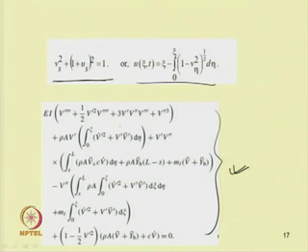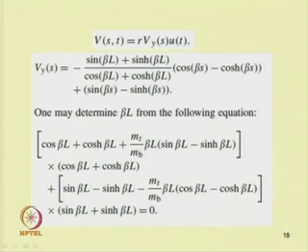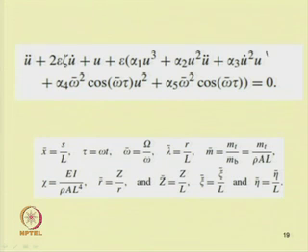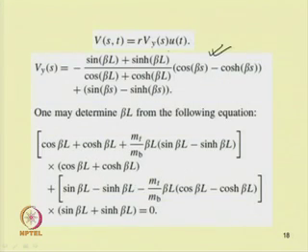After getting the equation of motion in spatio-temporal form, by substituting the shape function one can find the temporal equation of motion. In this case one has used the time modulation u(t), and the shape function is that of a cantilever beam with tip mass.